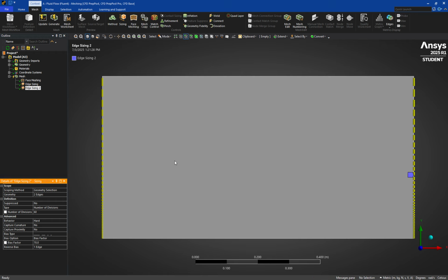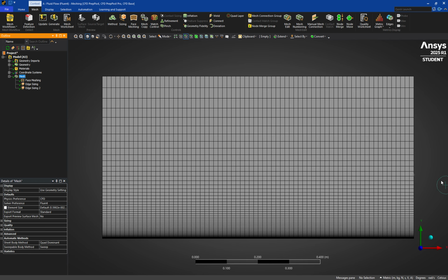That's alright, now it's matching on both sides. There we go. And then generate. Should be good here. Take a look at the mesh. Perfect. So it's more focused on the bottom where the top of our plate is here. Now I have more clustered mesh here in the surface. Now again, I click on generate mesh. It takes very quickly to generate this mesh because it's very easy.